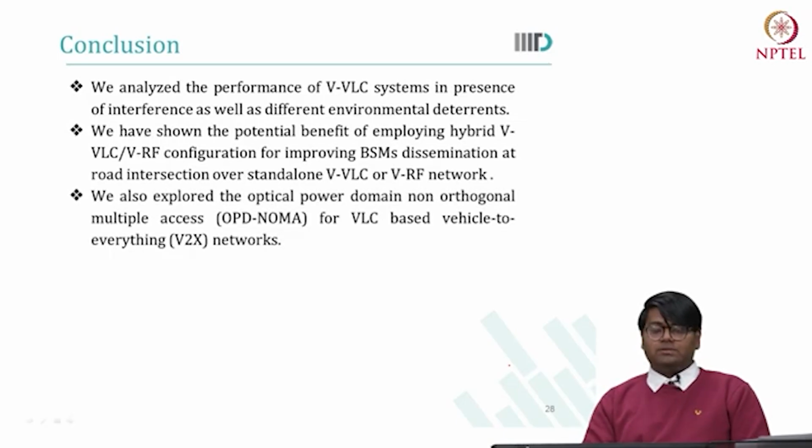Finally, we also explored optical power domain non-orthogonal multiple access for VLC based vehicle to everything network. We compared the performance of the proposed downlink OPD NOMA based V2X network to RF NOMA and showed that the OPD NOMA based V2X network offers improved performance in terms of outage probability.